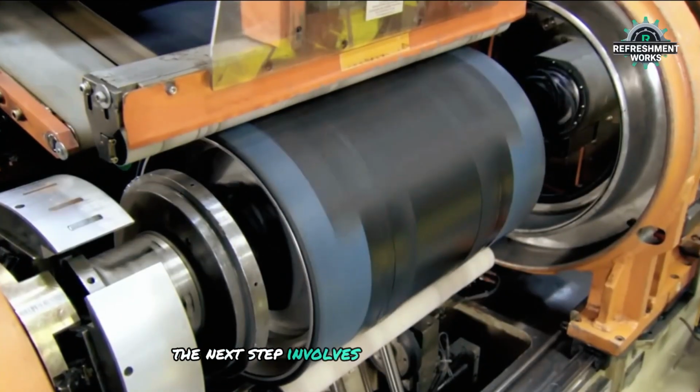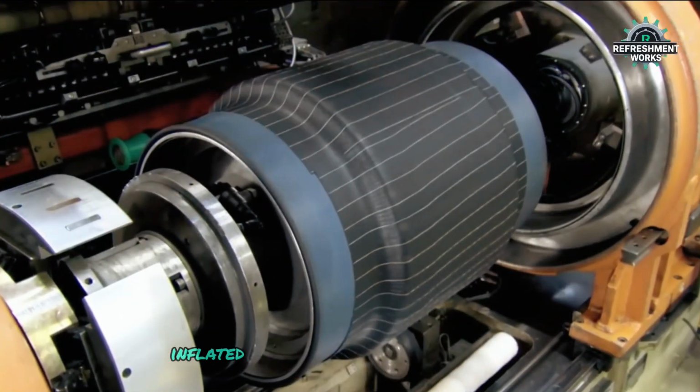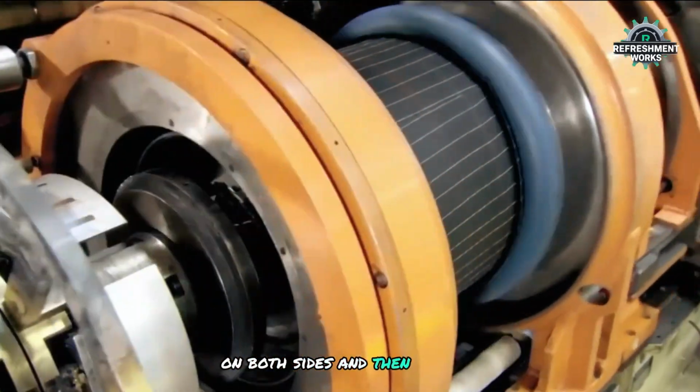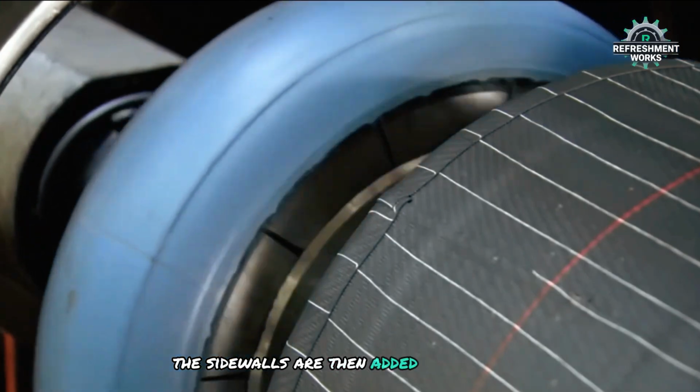The next step involves adding beads to the tire. Inflated bladders roll the rubber around the bead on both sides and then retract. The sidewalls are then added to the beads.